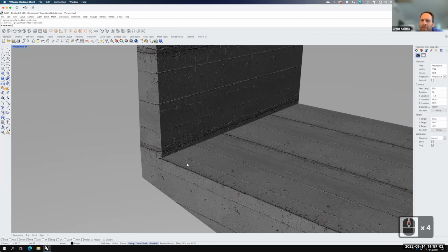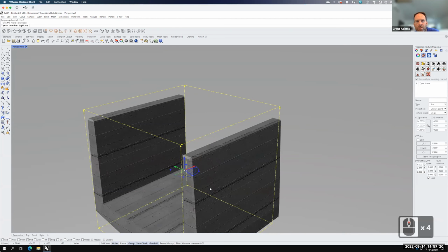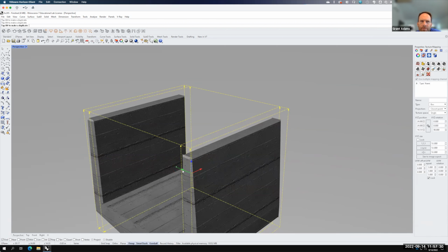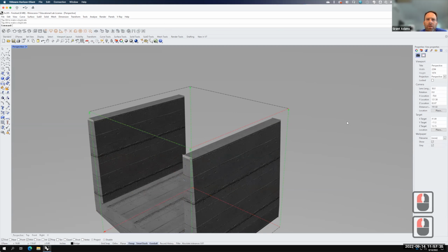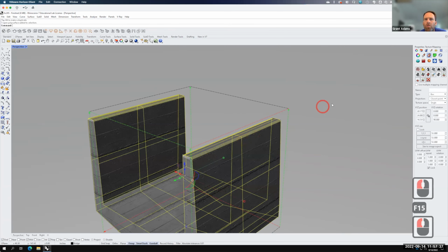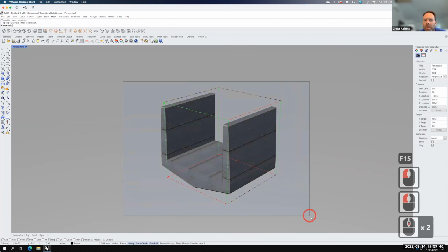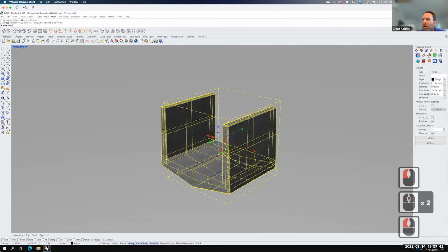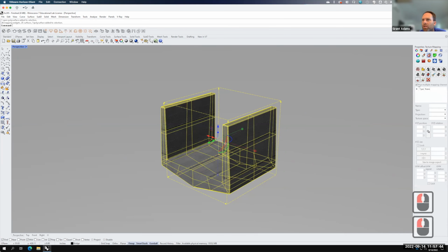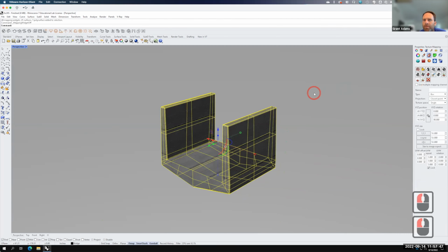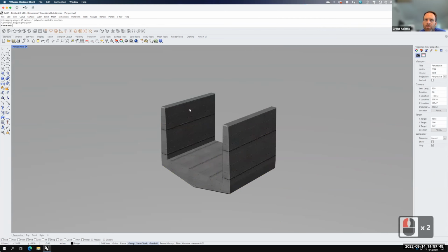If I don't like the way the tops are showing, remember, I can rotate those. Let me hold down Shift so it jumps to 90. And then I can move those side to side until I get the top the way I want to see it. Like that. So I'm just tweaking, using that mapping widget to adjust my texture mapping. Let me select it all again. I'll go back to my texture mapping, and I'm going to hide the mapping widget. And now I'm left with just this piece.